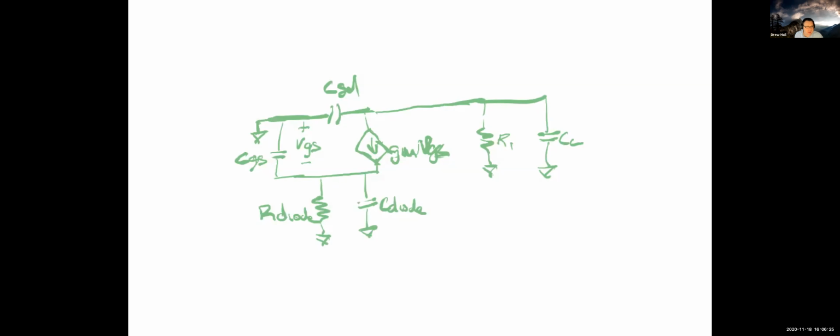All right, so ZVTCs, what we need to do is we need to go through this and we have to pick one capacitance at a time. And we're going to then solve for the impedance that we see at each of those nodes. So some of them are pretty easy and other ones are going to take a little bit of work. In particular, this CGS and this C diode, these two elements are in parallel. They don't look like it from the drawing, but one node is connected to VS, the other node is connected to ground. We could lump these together into one capacitance.